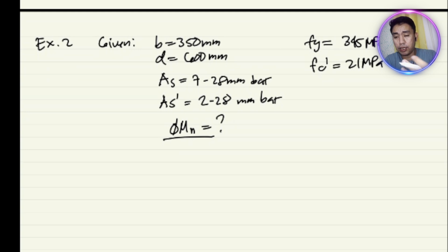So, we are tasked to investigate kung magbago ba yung loadings, maximum loads on moments and even shears na ma-encounter ng section kung safe ba doon sa bagong function ng building. And then may mga cases rin na kung masira yung building, and then, we are tasked to investigate given the section and then compare to the design load kung safe ba siya or adequate.